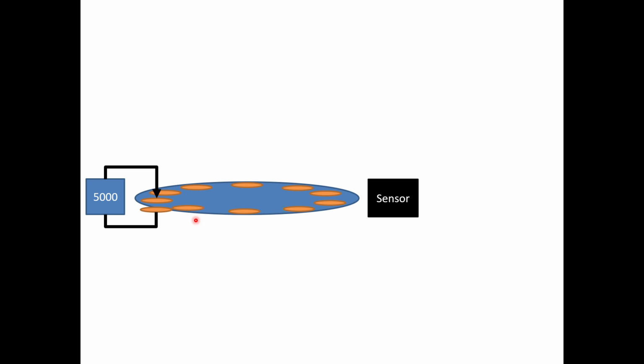One of the other ideas is to have an arrangement that charges alternating disks, positive and negative. That would give us a square wave, or probably a triangle wave, going by the sensor, which would give us the two-directional thing we're looking for. Because we kind of need to make it work in both directions. Somebody could say, "Oh, you just have drift or you just have bias." But if we can show that alternating charge on those plates gives us equal and opposite measurements on the sensor, that would be a very clear and hard to disprove experiment.